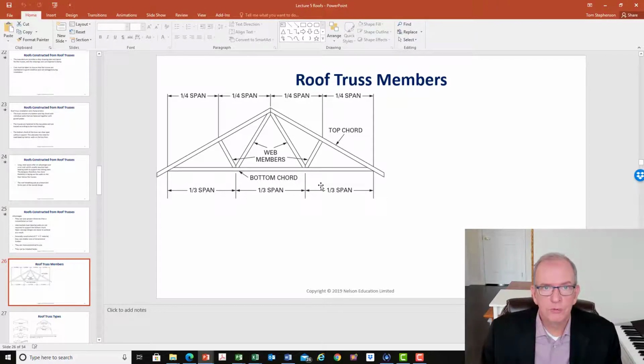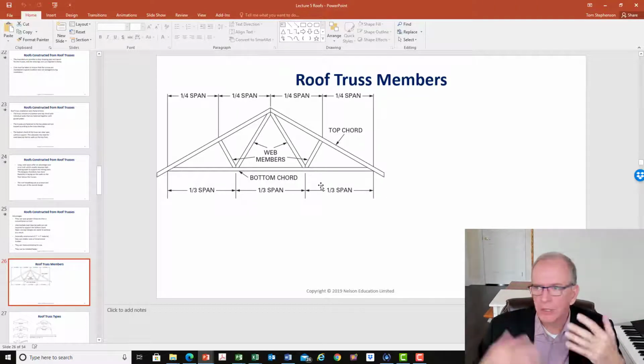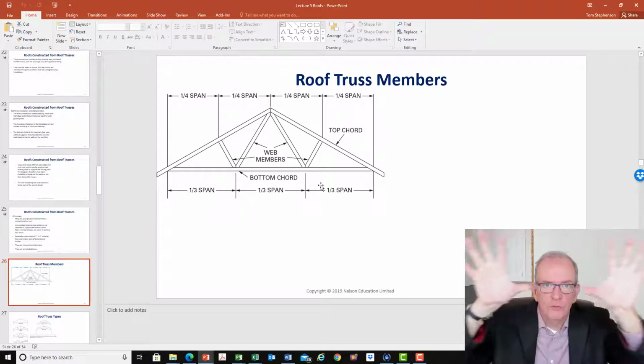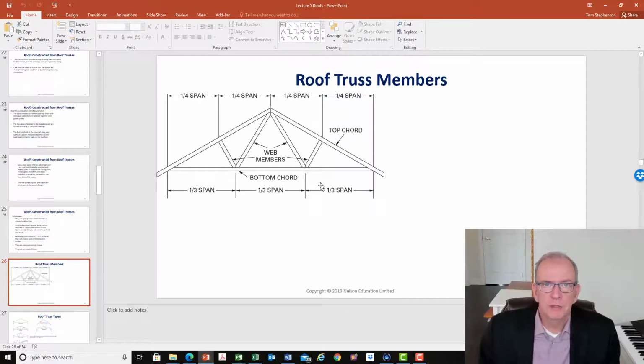Huge advantage of roof trusses is, though, you can span super long distances and you don't have to have load-bearing walls in the middle. There's some roof trusses you have to, but generally like a hip type roof or something like that, a more generalized roof like on most of our drawings, all the interior walls on the second floor are non-load bearing. So that's a big advantage compared to having ceiling joists with a cut roof and massive rafters, and then they're still not long enough to easily span some of the distances of our big houses that we tend to build today.